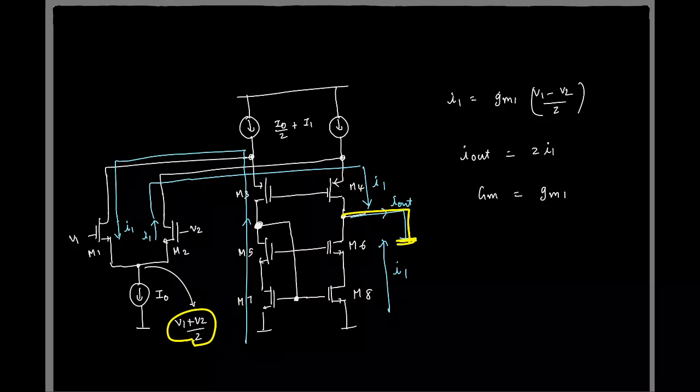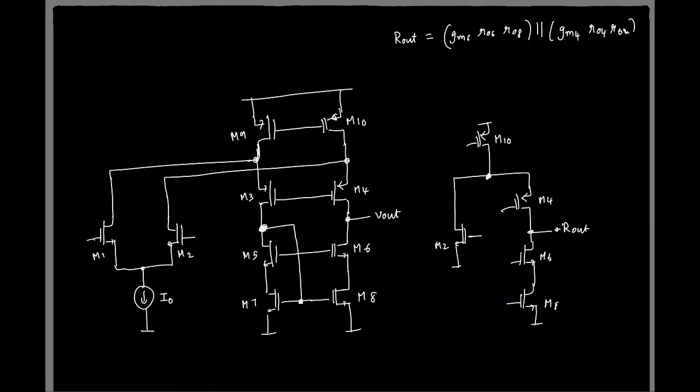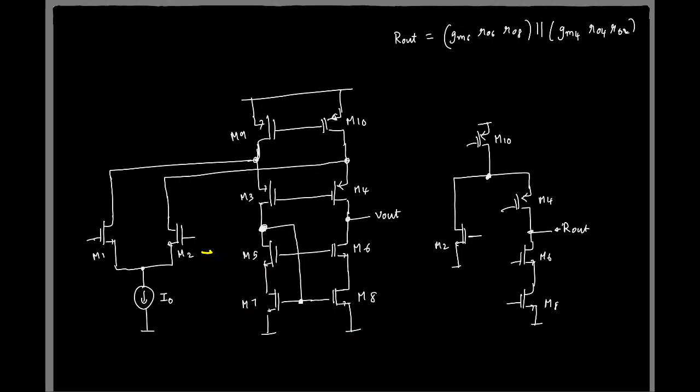Fine. For finding the output impedance, we don't do anything to the output, right? We directly apply some test voltage here and then find what is the current it draws. Okay. There V1, V2 is not there at all. That fine? For finding the GM, it is just a short circuit GM. So there I have to short the output and find what current comes.